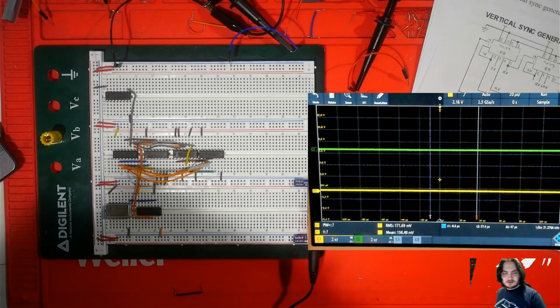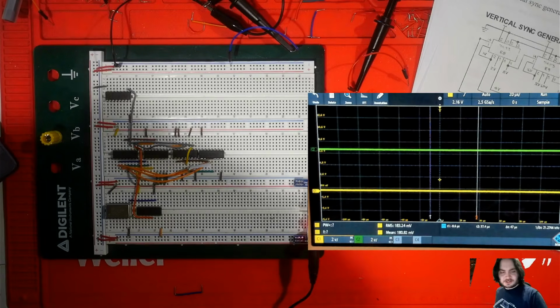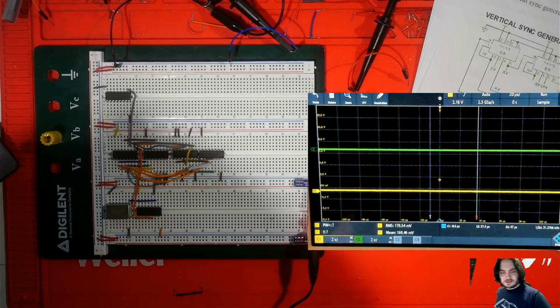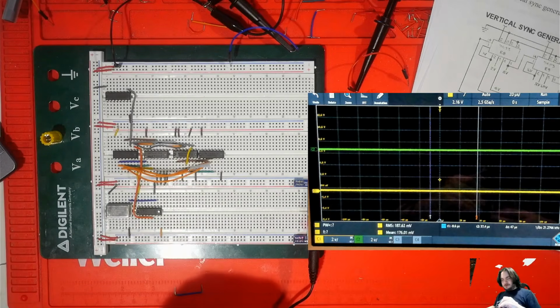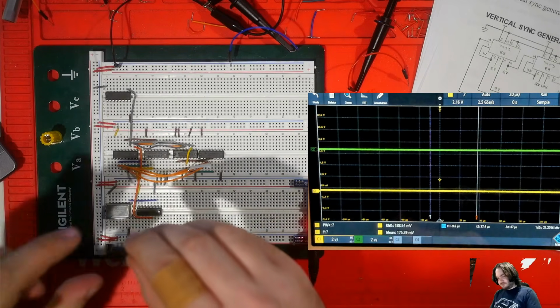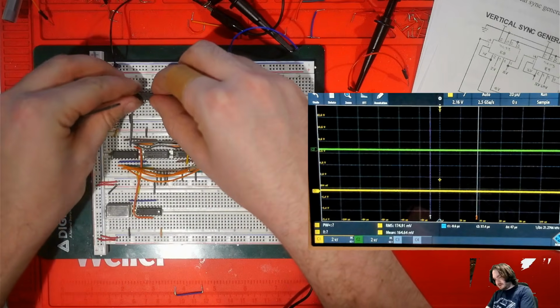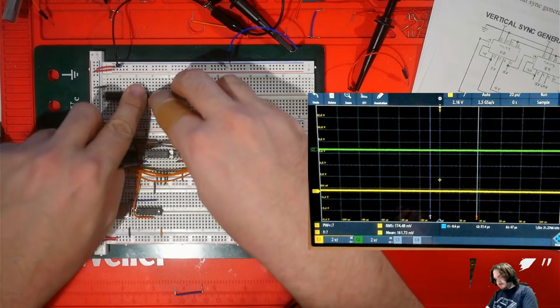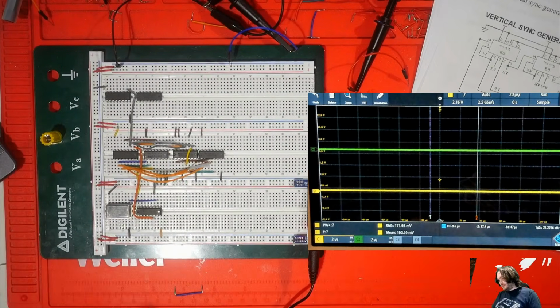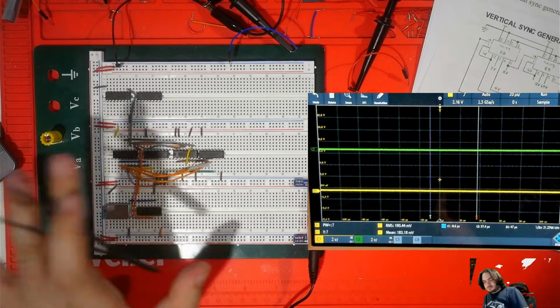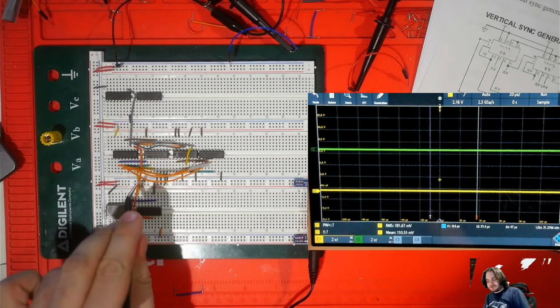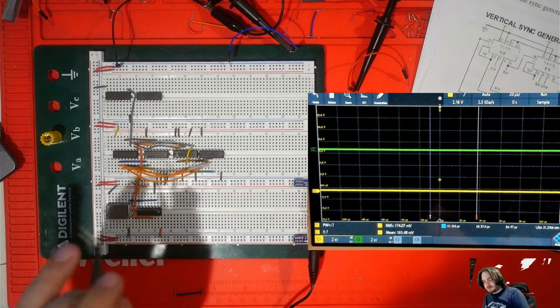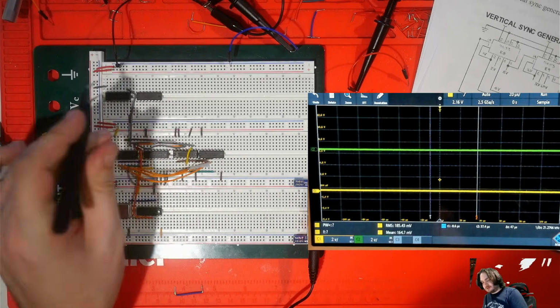So this guy wants to count to 262. The flip-flop we're going to use extends that by 1, so we're going to try to form the basis of counting to 261. This uses 1V, 4V, and 256V. Similar to how I was calling these signals H1, H2, H64, or 64H, these are going to be 1V for vertical.